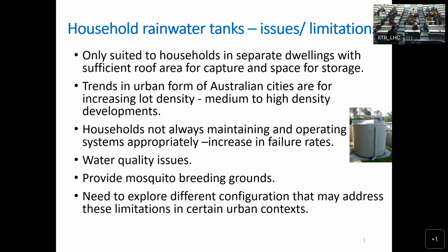So my response to that is that I'm talking about daily water balance, not even monthly water balance. We are using the climate data on a daily basis. There are even software packages which can use a 6-minute model, looking at every 6-minute demand and supply.